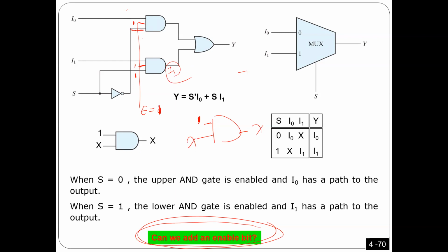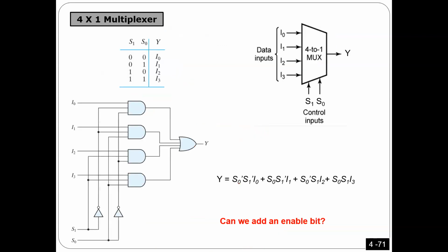This is just a very small multiplexer. This multiplexer has only 2 inputs. I'm going to make it bigger, but the idea is the same as what I explained, the same as the decoder. All I did was make 2 modifications. Number 1, all the outputs of the ANDs are connected using OR, because this one has only 1 output. In the decoder, I have 2 to the power n outputs, so there is no OR there. Number 2, in the inputs, I connect I0, I1, I2 to every AND. So let's see the next case, which, as you will see right now, is very similar, not identical, to this case.